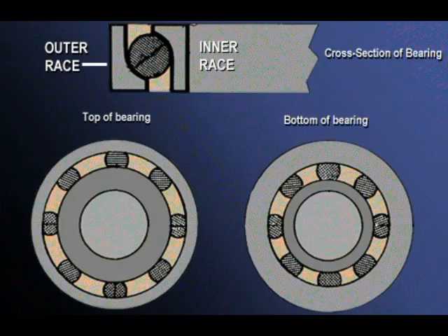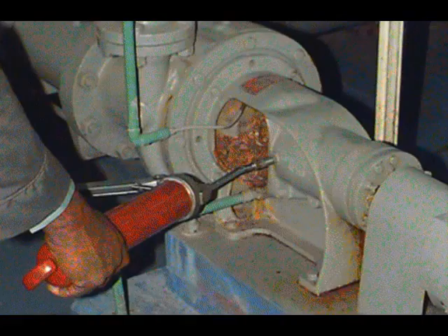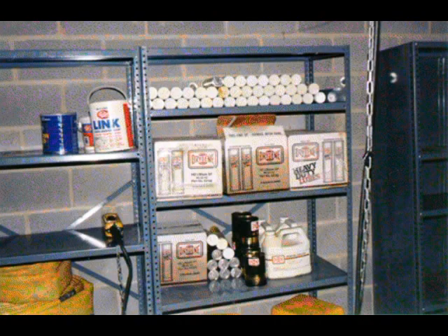When the ball bearing is looked at in cross-section or taken apart, the inner and outer races are more easily seen. A critical maintenance factor for proper operation of any bearing is proper lubrication. Without proper lubrication, bearings will overheat and seize. The bearings in any unit are in constant motion. It is very important to use the correct type and the correct amount of lubrication.